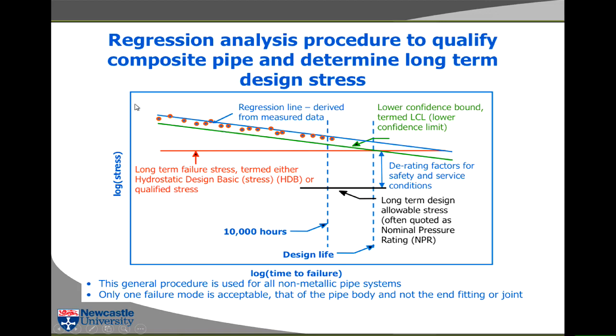You can do this over a period of time, up to about 10,000 hours, that's a bit over a year, and then you extrapolate that into the future to the design life. And that enables you to create the rating for the pipe.